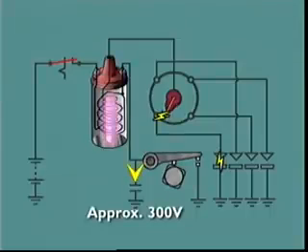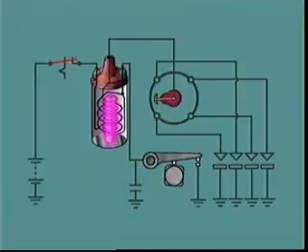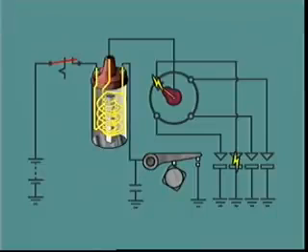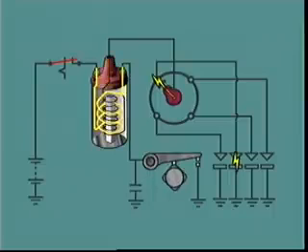By the time this has occurred, the gap between the contacts is too wide for a spark to discharge between them. This abrupt interruption of the primary circuit assists in the rapid collapse of the magnetic field, and hence an increase in the value of the voltage induced in the primary and secondary windings. As soon as the secondary voltage reaches a value where it bridges the gap across the spark plug, the voltage in the primary circuit falls to a value below that of the charged capacitor.